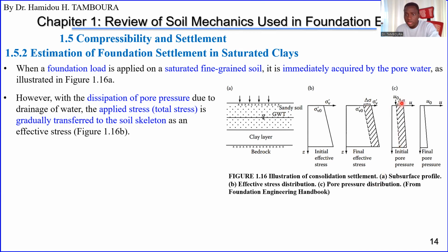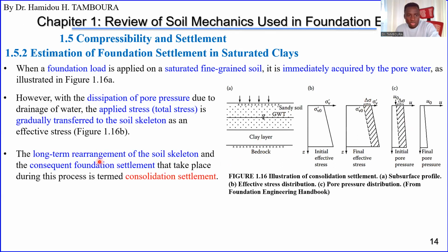So sometimes this transfer will take a long time. So there is a long-term rearrangement of the soil skeleton after the water is gone, at equilibrium of water pressure, then the rearrangement of the soil particles will start, and the consequent foundation settlement that takes place during this process, we call this consolidation settlement.